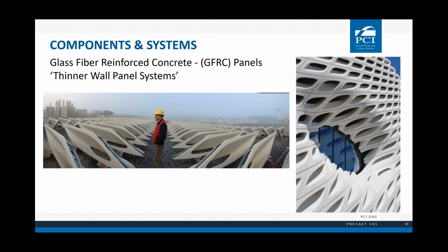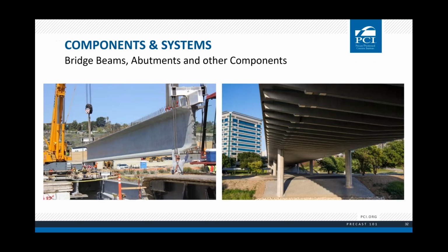Glass fiber reinforced panels are gaining in popularity because of their light weight. The best way to describe them is a thin skin of concrete attached to a steel stud frame. Not all precast producers produce a thin wall product or GFRC panels, and in many cases, a solid precast panel is a more economical or better choice based on how the mass of solid concrete contributes to the overall structure's performance.